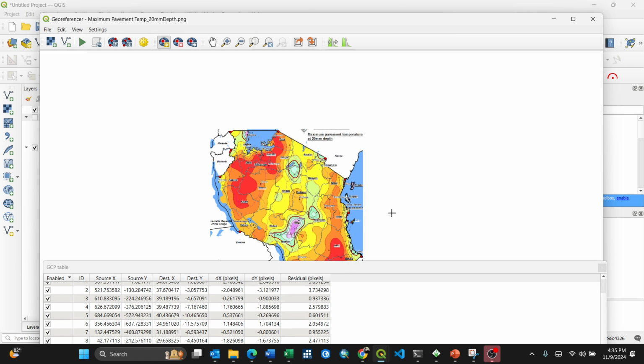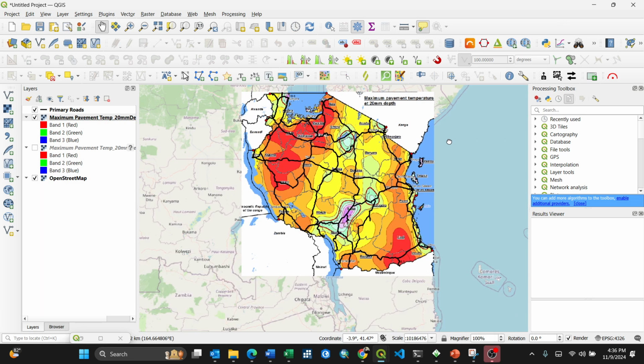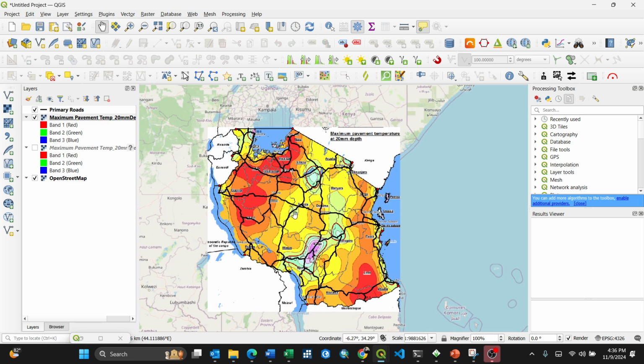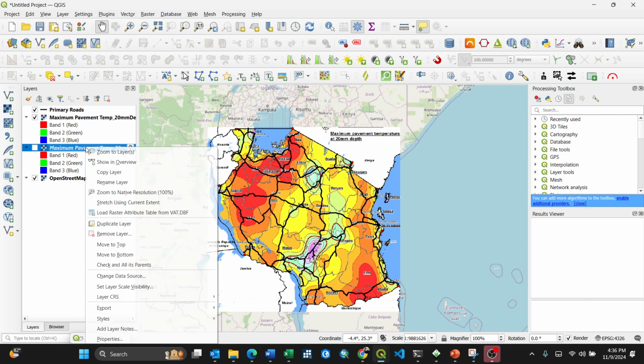So by pressing OK, now pressing this one, it will be active. Start georeferencing, or you can click it somewhere here, start georeferencing. So by clicking, the georeferencing is actually, you see, successful. So opening my QGIS now. Let us open our beautiful QGIS. Let me minimize this. Voila! You see, our map now appears here. And we can see the roads are superimposed. So now, you see, this is the one which is not georeferenced, and the one which has been georeferenced. So I remove this.